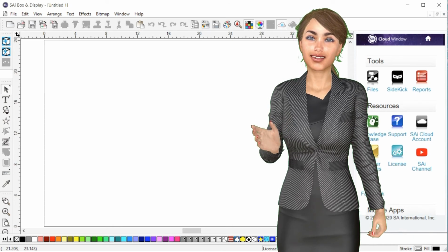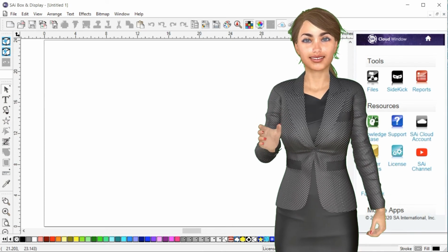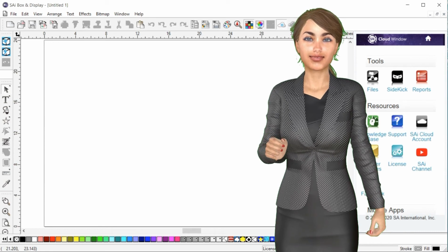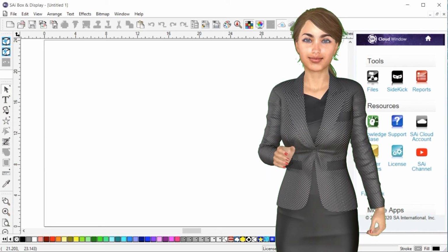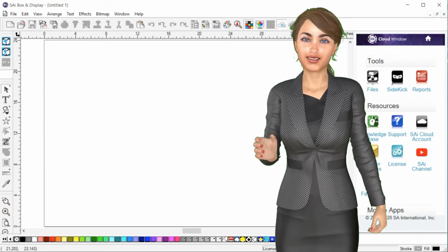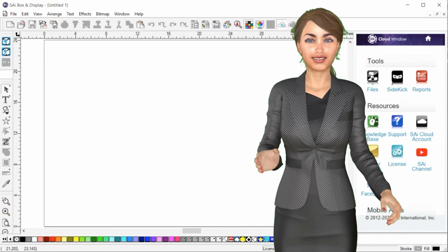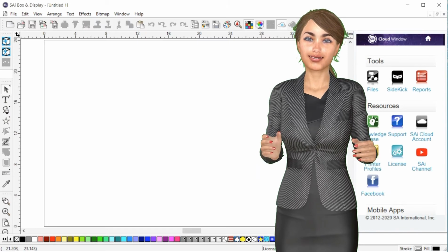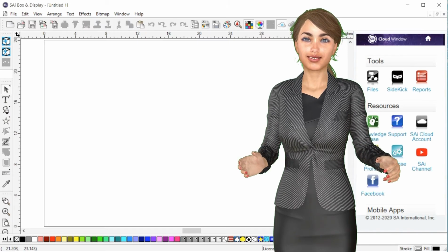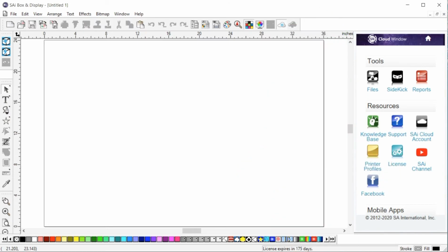We are going to add a shape to the back of the display that we'll use as a pattern for a cutout. Next we'll send the design back to the box designer and use the Show Texture in Construction View option to make the image visible. Using a hole machine step we'll cut out our shape and finally we'll add this new display to our user library. If you're ready, let's get started.